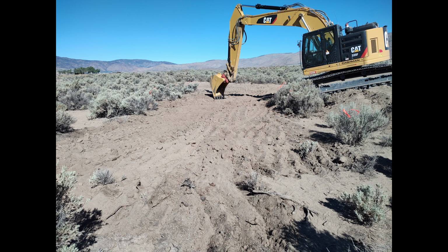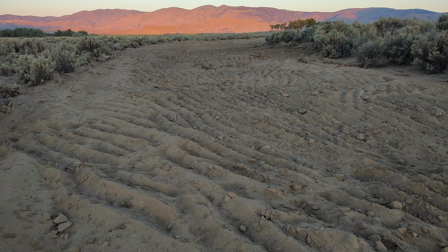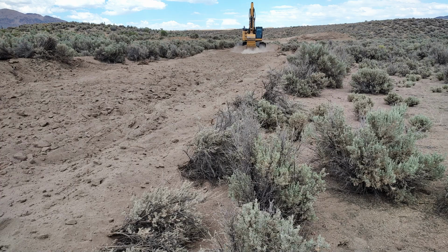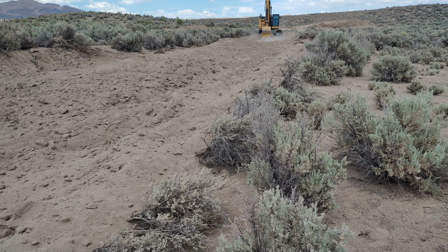There was no need to armor the spillway with rock because it was built with a slope of less than 1/10 of 1%. We did not use the rough and loosen technique in the spillway because the pits and mounds could concentrate the flow of water into narrow channels and cause erosion. We did not place logs or piles of brush in the spillway because these could concentrate a flow of water and also cause erosion. We asked the people managing the ranch not to drive motor vehicles in the spillway because that could leave ruts that would concentrate the flow of water and cause erosion.